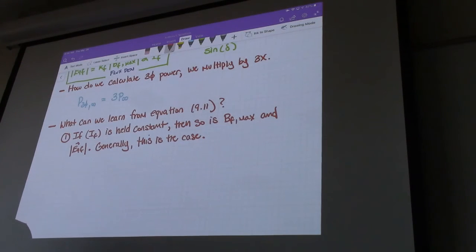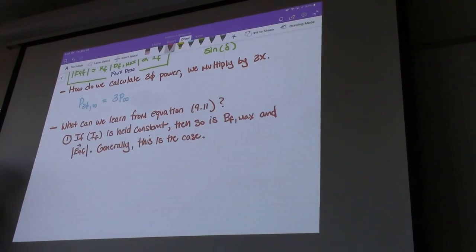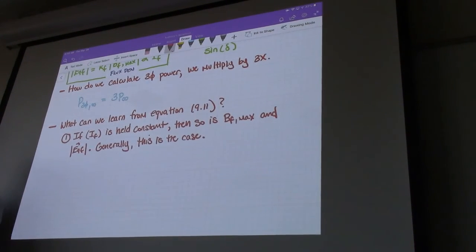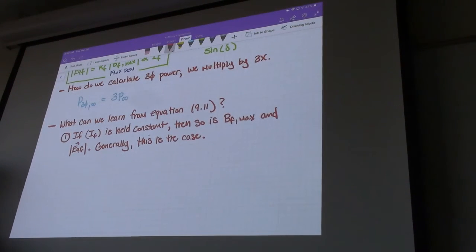So what we're saying there is that when the generator is operating, the control system or the operator or whatever body you want to use to represent whoever's applying IF, they're not playing around with IF as the generator is operating, right? It's not a value that's generally being increased and decreased. So for the purposes of our example right here, we can say, let's assume that IF is staying constant. Now we'll see later on that IF can be used in a control algorithm for a synchronous machine to affect reactive power output. And it's another way of essentially performing power factor correction is by manipulating the IF value. But for this right here, let's just say we're not trying to do any sort of power factor manipulation, and so that value is staying constant.